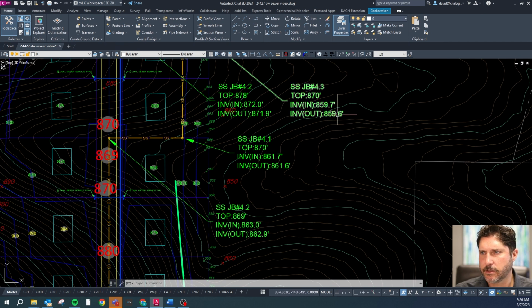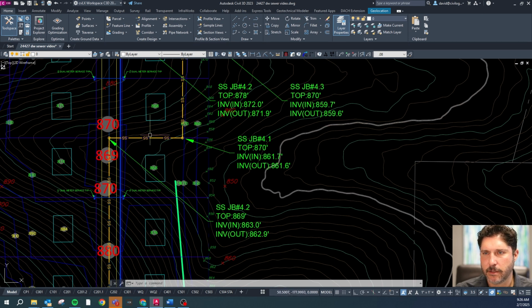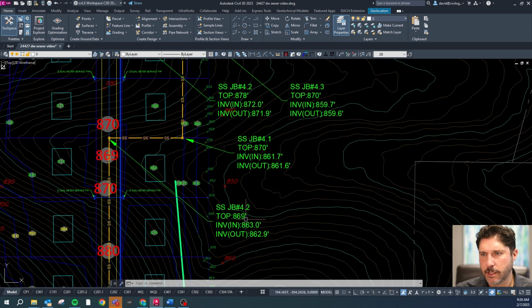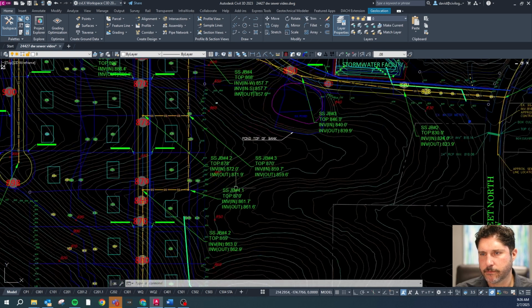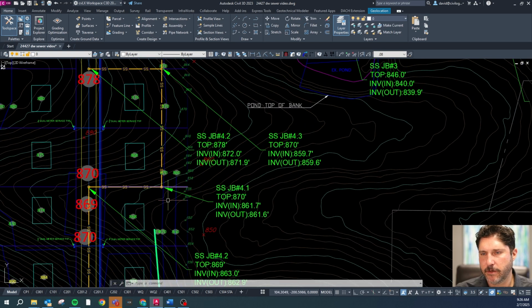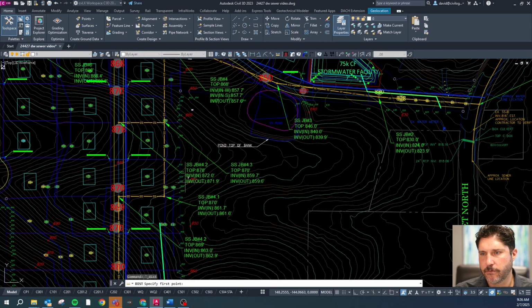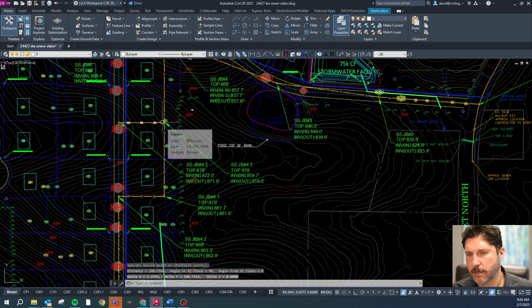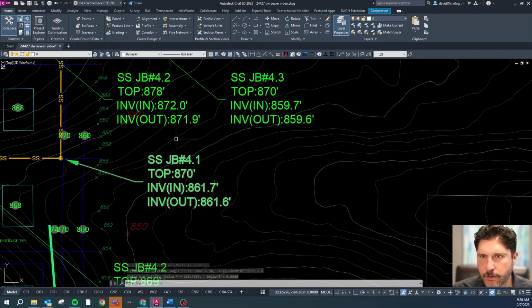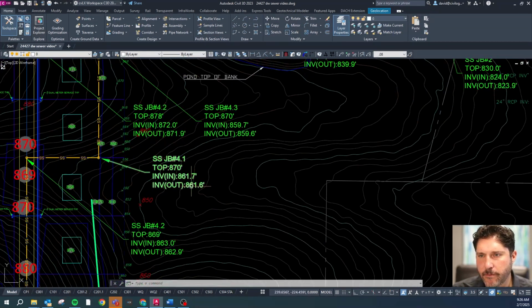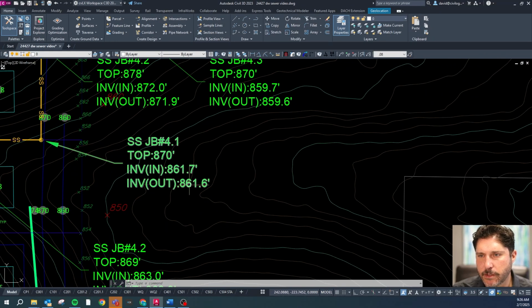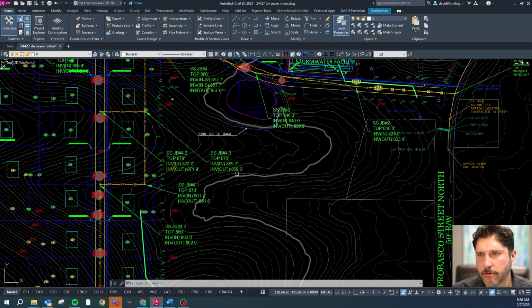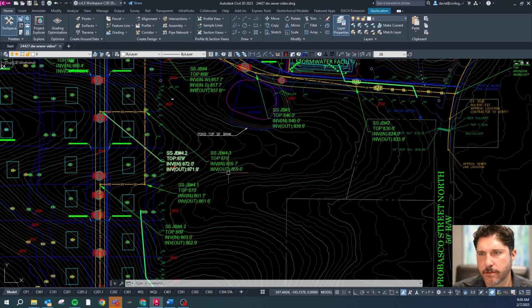We just want to check that this seems 10 feet deep. Does it need to be that deep? So we were at 69. We were 6 feet there. We went down to 1%. 62.9 to 61. So that's 9 feet deep. And then we go from 61.6, and that's 180 feet, which is 1.8. So we subtract 1.8 from this, and that's going to be 60.6, 59.8, 59.6. So yeah, that is the minimum.